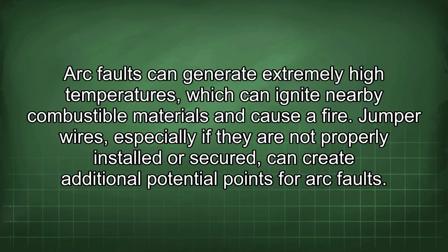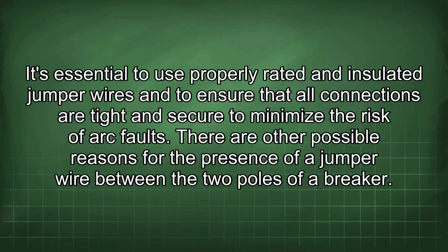Arc faults can generate extremely high temperatures, which can ignite nearby combustible materials and cause a fire. Jumper wires, especially if they are not properly installed or secured, can create additional potential points for arc faults. It's essential to use properly rated and insulated jumper wires and to ensure that all connections are tight and secure to minimize the risk of arc faults.